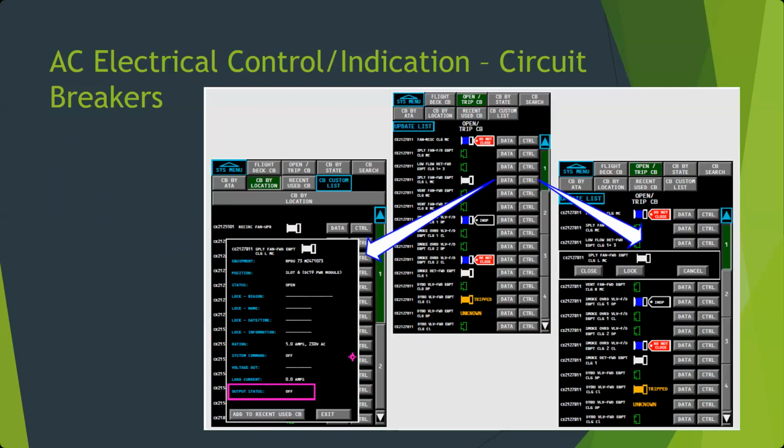You can see just below that, supply fan, FD equipment, can't remember what that is. There's a green breaker pushed in. A little further down, supply fan forward equipment is white. That means it's pulled out right there. And then further down, about most of the way to the bottom, outboard forward equipment, cooling, you can see a tripped breaker, where it goes in like a yellow-orange with the trip word next to it. So you can pull a breaker, that's the white one, or you can have a breaker in a trip position.